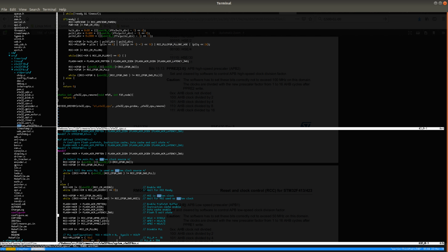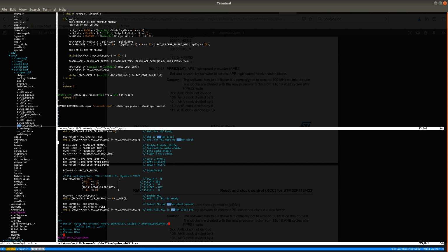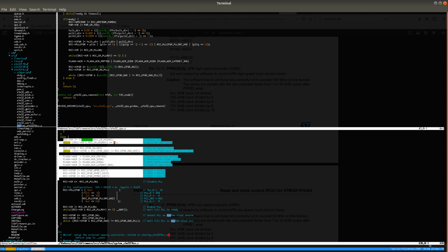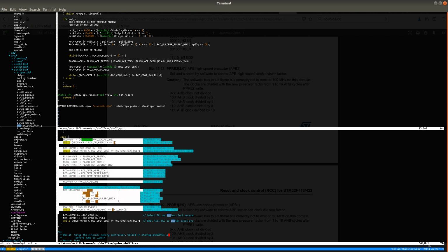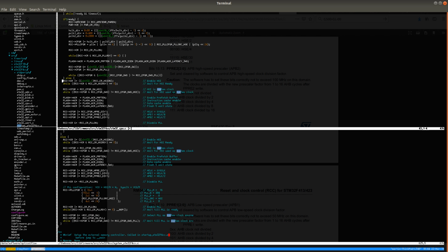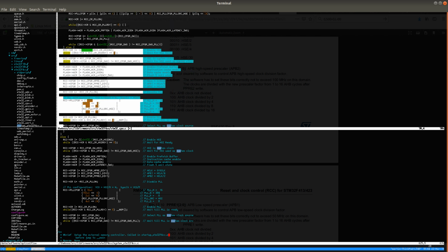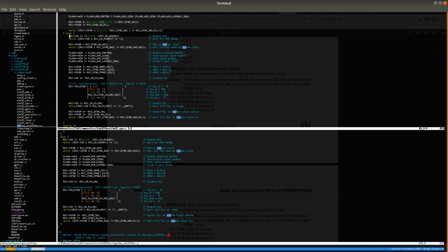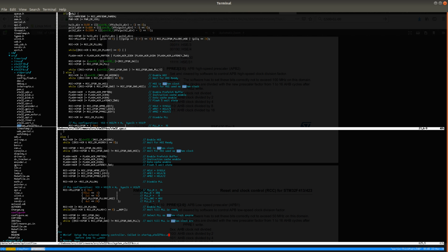And for the internal oscillator, they use hard-coded values, which we don't need to. Actually, it could be good to be able to set the actual frequency of the chip, but the proper way to do it would actually be to specify the target frequency in the device tree, and then to calculate the necessary division values that most closely match that desired frequency.